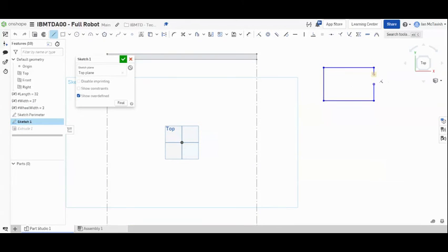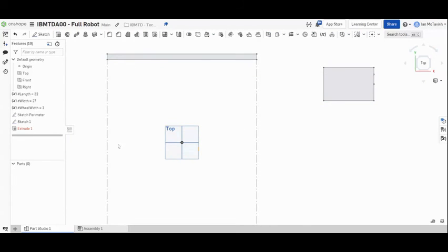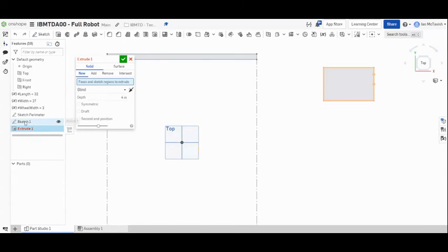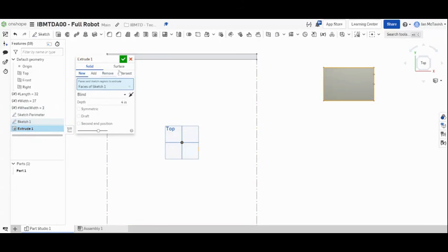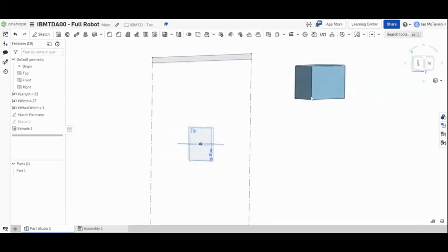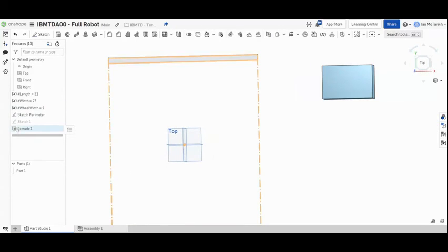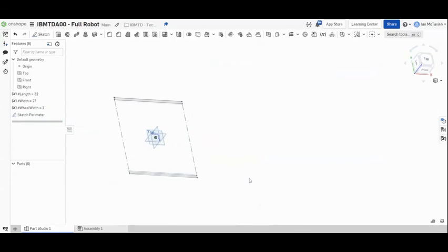If I close the hole, so I'm just going to add a line between them and make it solid, you can see that that extrude is now going to work because it's a solid shape. So that's really important. And if you have done that properly, you should have gray down here.